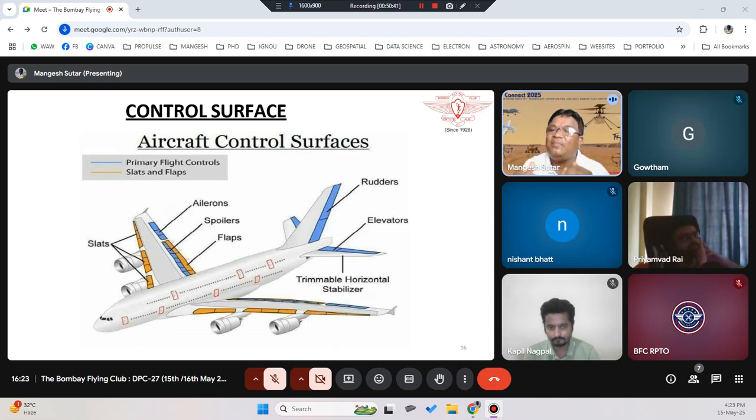Okay, so this is applicable when you land. You will see the spoilers coming up. If you have taken a seat near the wing, you will see these spoilers getting activated when you land on the ground. The moment you land on the ground, the spoiler will be up, because the pilot wants to increase the drag on the aeroplane so that it stops very quickly.